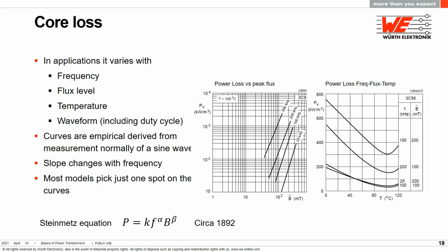Switching power supplies typically use rectangular waveforms, so it's one of the things that we have to deal with. Square waves, that is 50% duty cycle, are easy because generally they have about 15% lower losses than the curves indicate. Just use them as they are, which gives built-in margin. Rectangular waves, those with on times less than 50%, get more inaccurate as the duty cycle decreases.